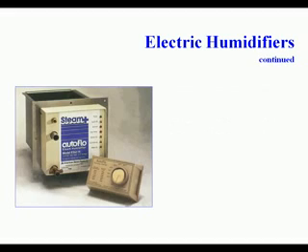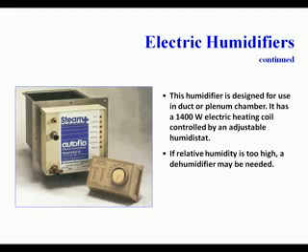Most heating buildings in temperate zones need humidifiers during the winter season. Electric humidifiers are used by buildings with steam, hydronic, or warm air heating equipment. Advantages of electric humidifiers are ease of installation, flexibility of location, and accurate relative humidity control.